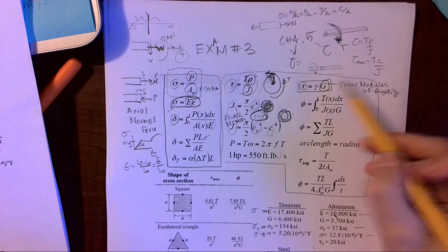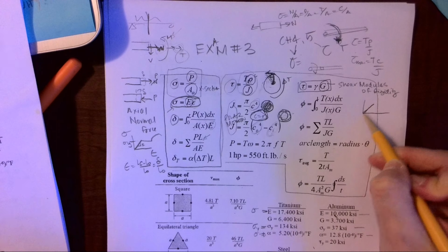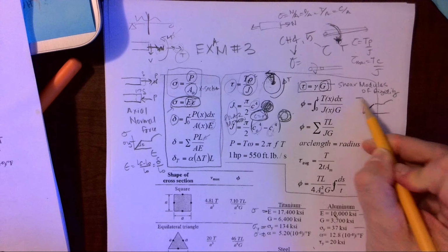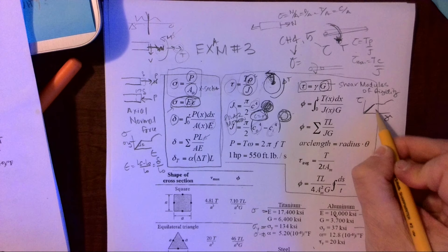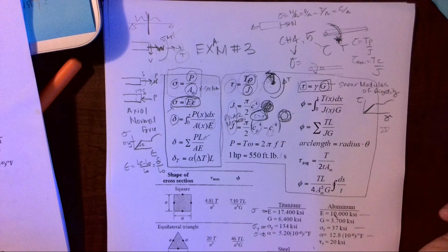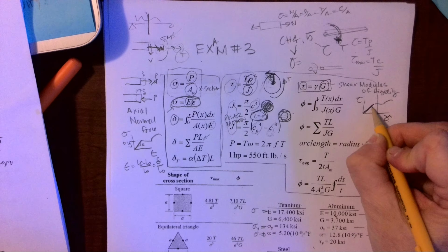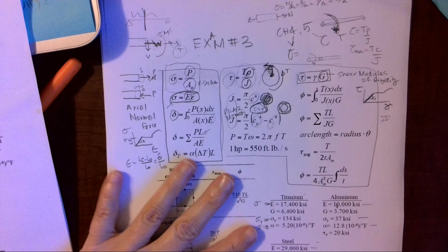It again is that value in my linear region of whatever diagram I have that's a function of shear stress and shear strain. It is that skewing of my little tiny square, okay? This is G. G is the slope of the line in my elastic region.